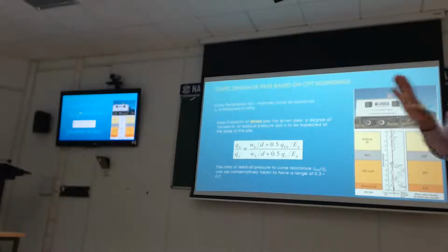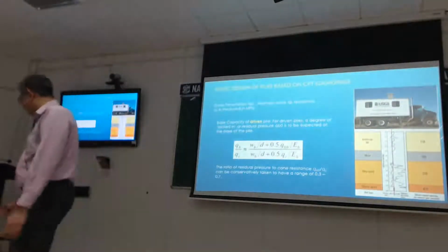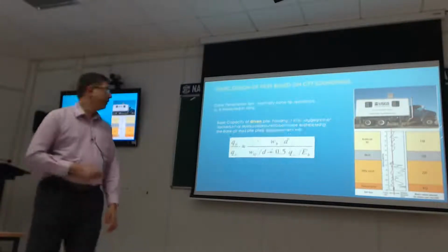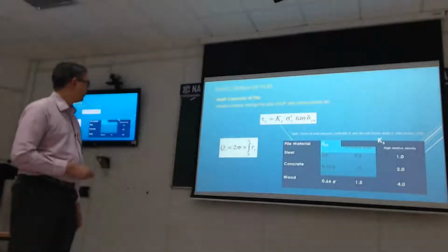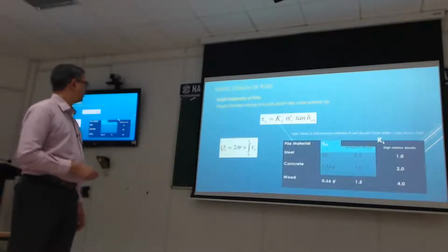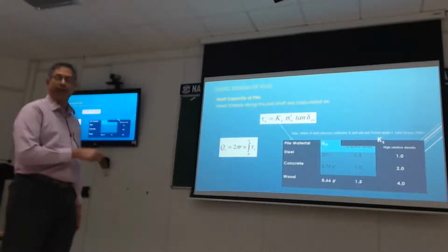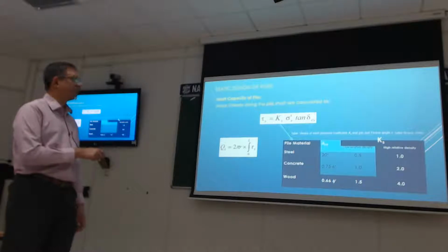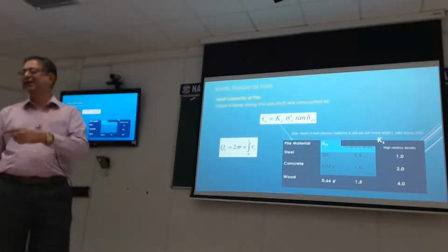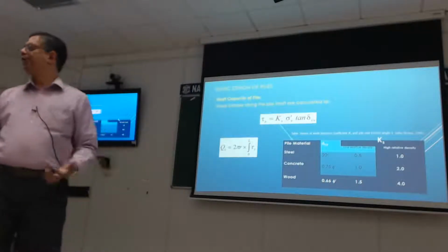And if I have big horizontal stresses, if I go back to even our basic equation we looked at earlier, this Ks factor will increase enormously because effectively Ks times sigma dash V is my sigma dash H. That is what's going up.